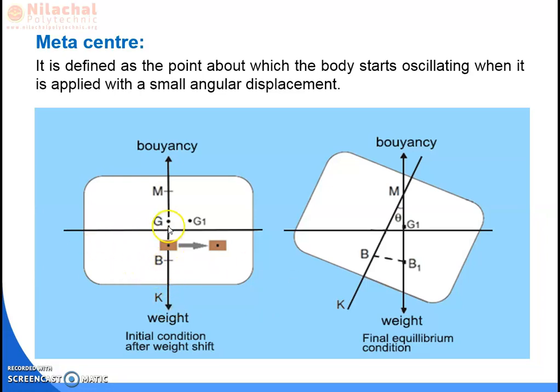In the earlier classes, we know about the upward force given by the water against the weight of body, the buoyancy force, which is also acting. The point B is known as your buoyancy force point, that is your center of buoyancy, at which the force of buoyancy is applied. We have seen the buoyancy force and the weight applied by the body upon the liquid, both are in a vertical direction. The center of gravity G and center of buoyancy both are on the vertical line.